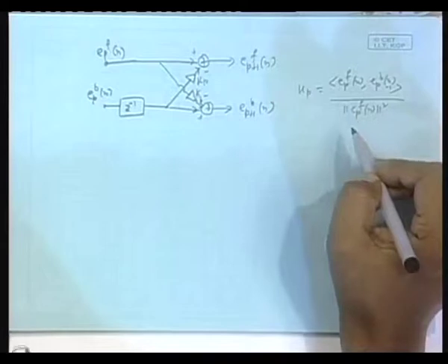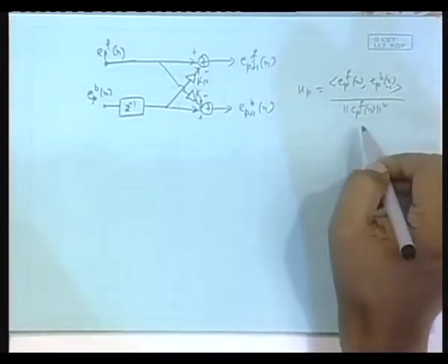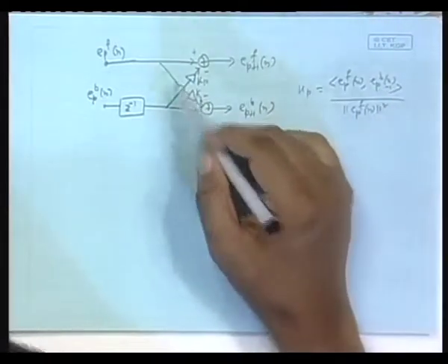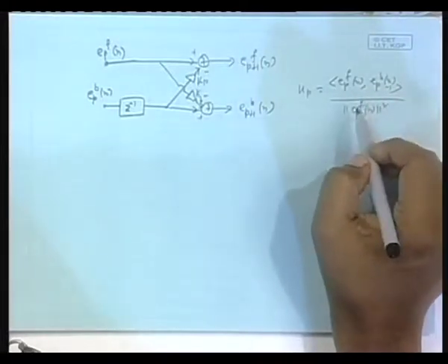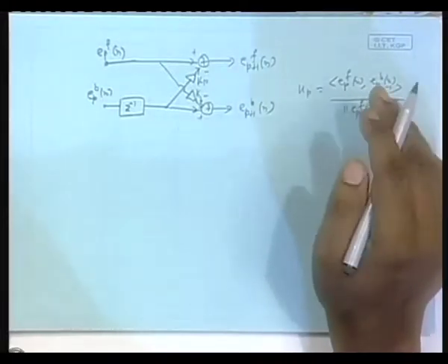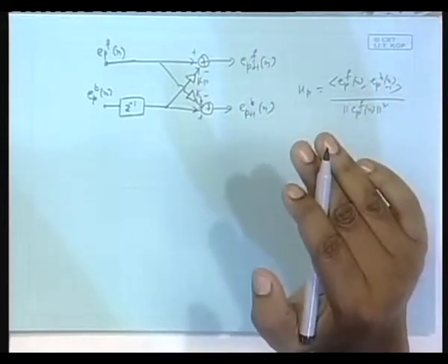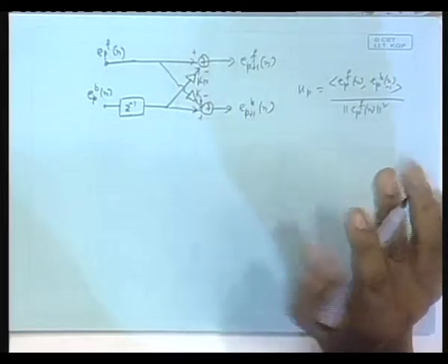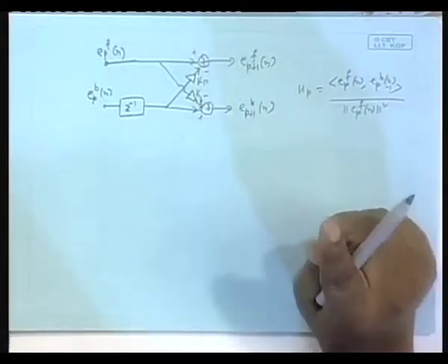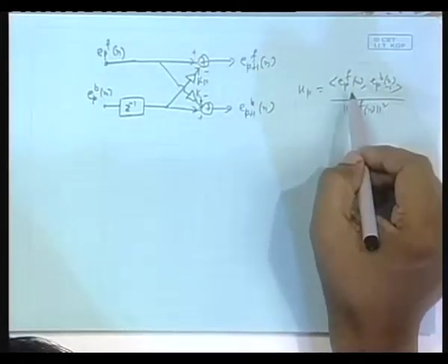We can recursively update this norm square, and also using the predictor coefficients you can evaluate this numerator thing, which I called delta p. So, essentially, given the autocorrelation values of the original process x n, the very first stage input, you can find out this Kp.